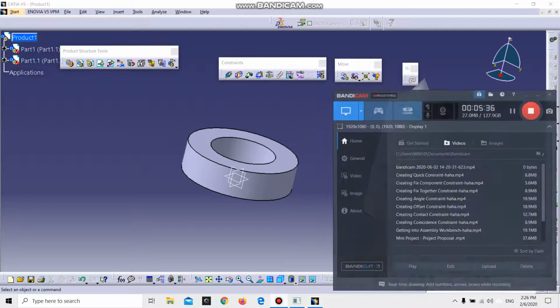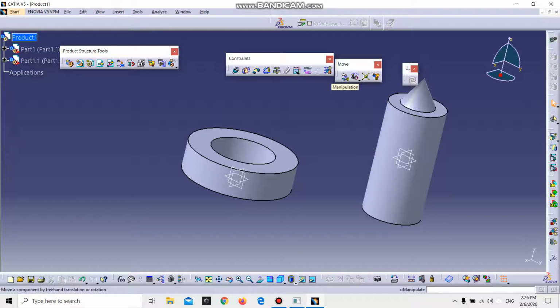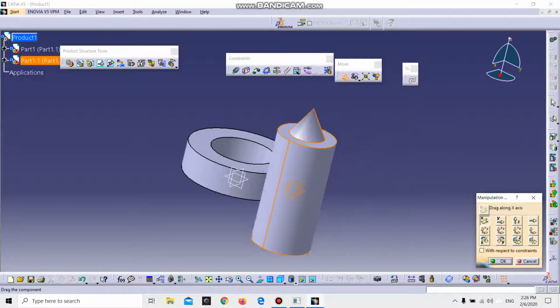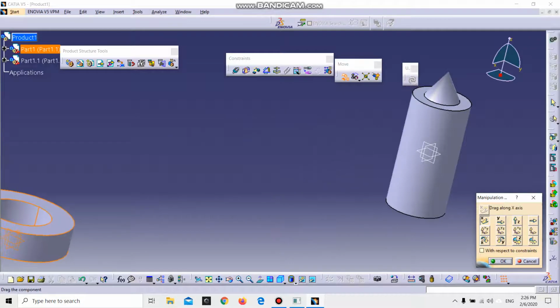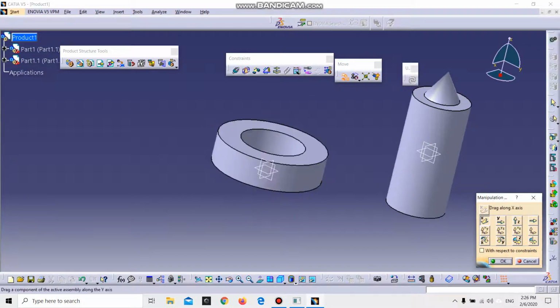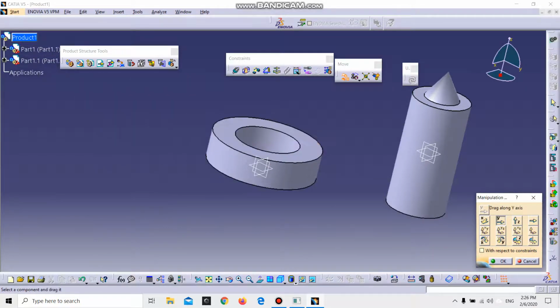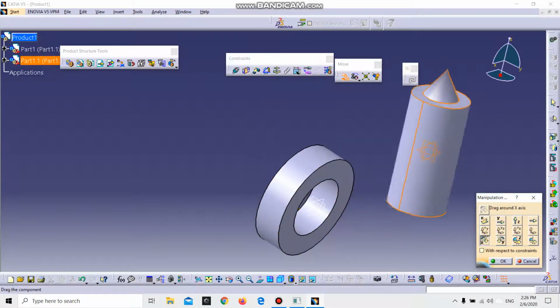Now I'm going to manipulate the orientation. So you can go to the move toolbar. If you click the manipulation, you can play around with the positioning. For example, this is X, only X, you cannot go up or down. If you press Y, then you can go along the other coordinate or another orientation. Similarly, if you have an X here. Okay, so this is alright.